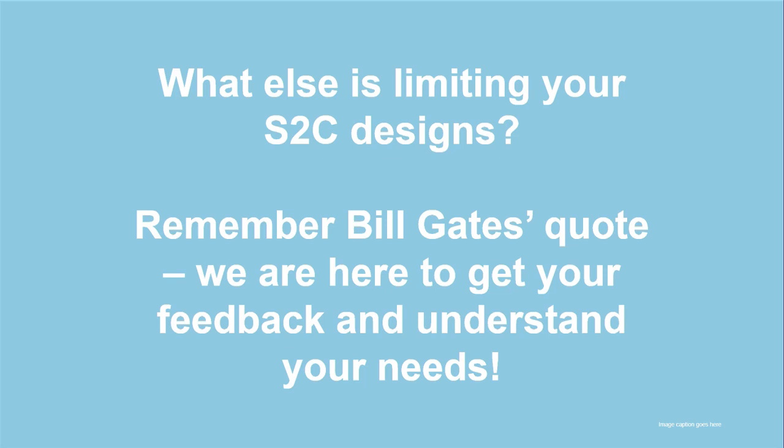In my line of work, essentially the problem that I see is that the structural engineer, me, we have a global analysis model, be it in SAP, ETABS, RISA, so a full building model. We need to look at the base plates. We have maybe hundreds of combinations. If you do an envelope load, you're essentially taking the worst of the worst of the worst, which doesn't realistically happen, right? The solution that I find is you need to check every one, and then at the end, see the sizes that you get, and envelope the sizes rather than envelope the loads.